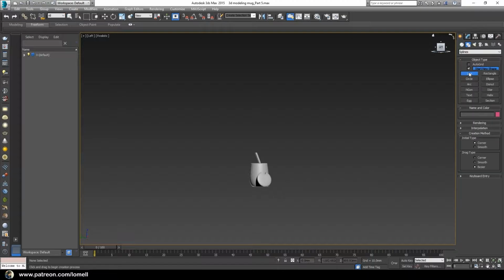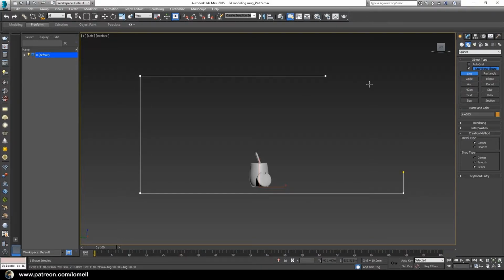Click that line, and let's start over here, just this far. Click here and hold the shift key on our keyboard so that we can create a straight line. Single click, single click, single click, and single click. Okay, and if you're done, right click and right click once more to end the creation process of this line object.